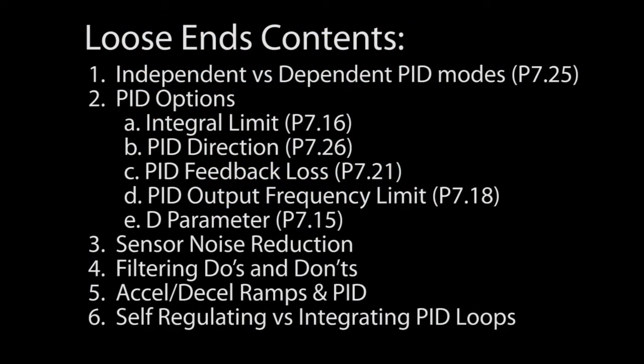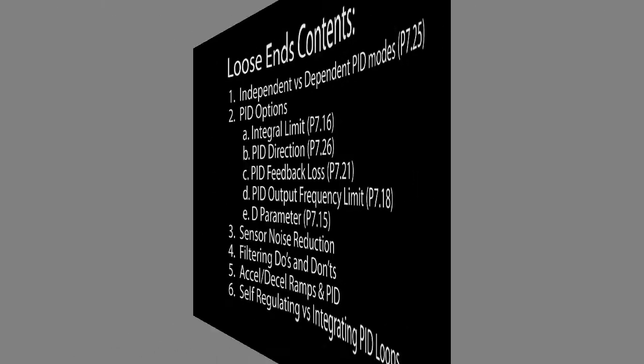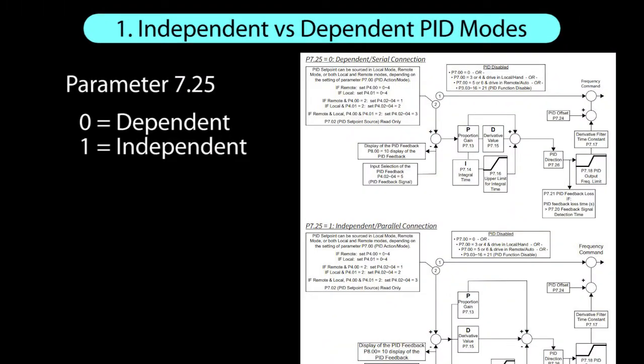These are the things that we glossed over or skipped in the previous videos that we'll cover in this video. When we set up PID, we had to choose between independent or dependent PID implementations. We chose independent because it makes tuning the PID loop much easier.